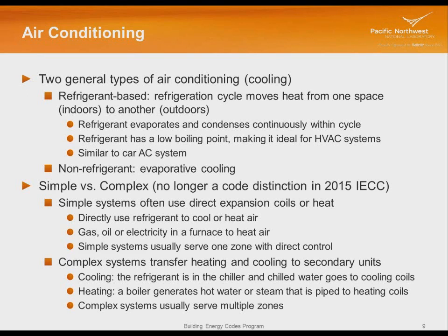This is similar to your car air conditioning system, where when you turn on the air conditioner, there's a little condenser under the hood, and it gets rid of heat, and it's extracting heat from the air coming through your fan. Non-refrigerant cooling is evaporative cooling, maybe also called a swamp cooler. Not typically used, but in some buildings they may use evaporative cooling to help with the cooling process or provide all the cooling if they don't have refrigerant-based air conditioning.